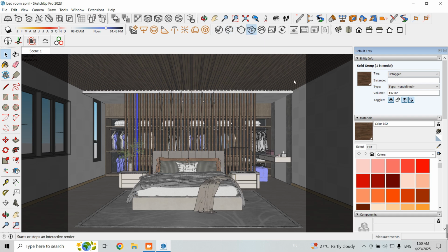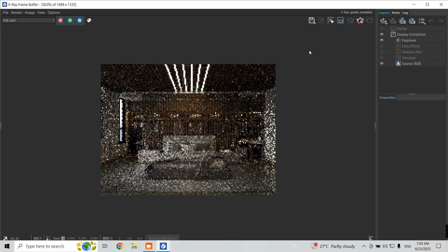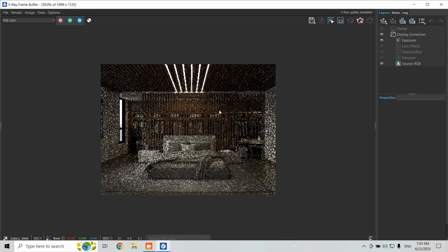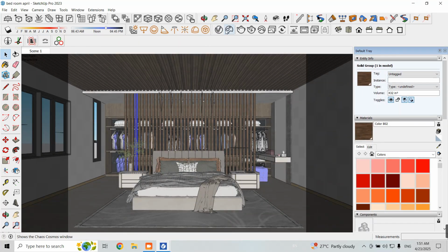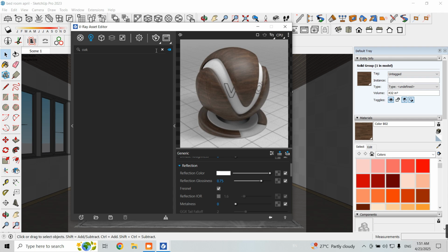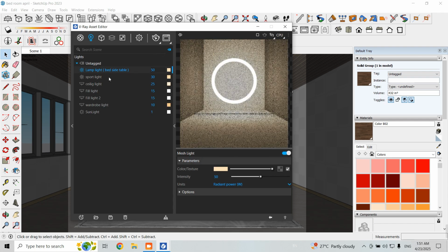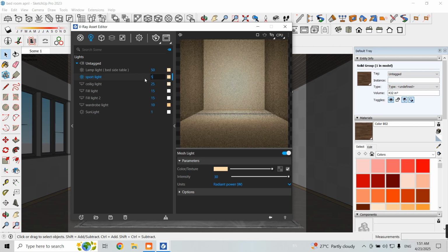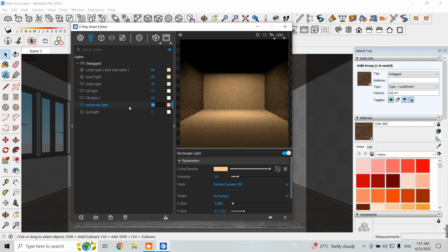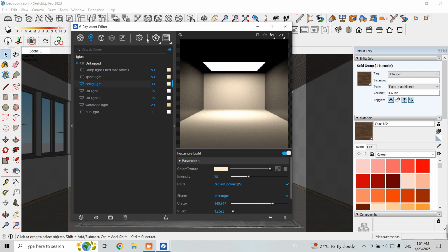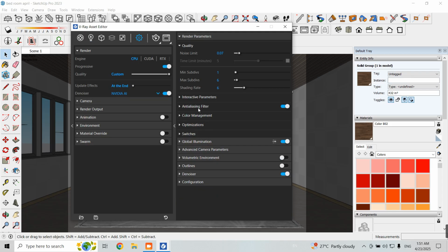Now let's see interactive rendering. The light intensity will not be too strong here, so let's increase it. I would like 20. I'm setting the size to 15. So fitting it like this. Okay.